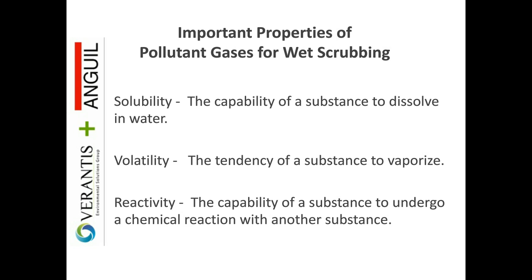It's important that we emphasize that solubility alone is not enough to make a given pollutant viable for scrubbing with water. There are many compounds that you will find good, reasonable, high published solubility data for, but they have very, very high vapor pressures above such a solution as well.